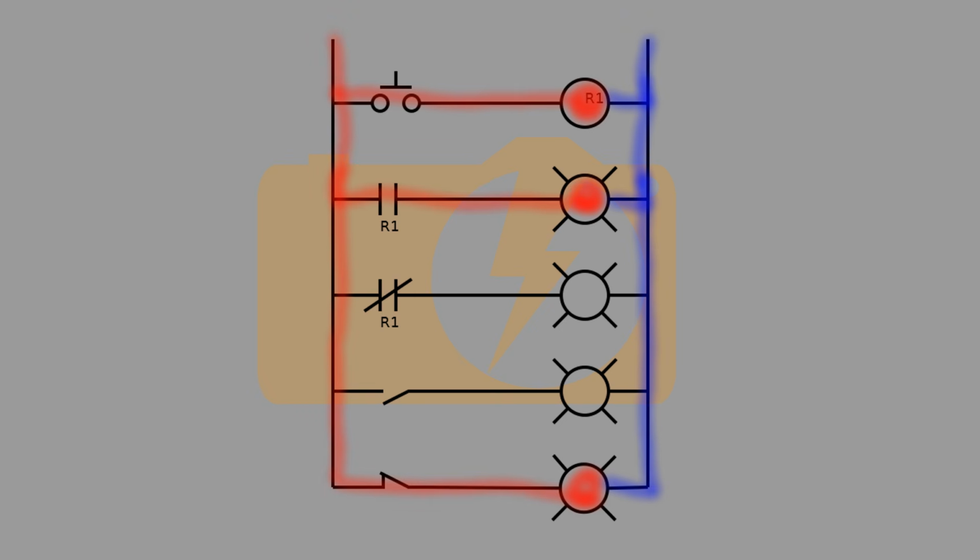Normally closed contacts act like an inverting output to a coil. When the coil is activated, the normally closed contacts will open. The switches on the last two rungs do not change state. This is because they rely on an outside action in order to be activated or deactivated.